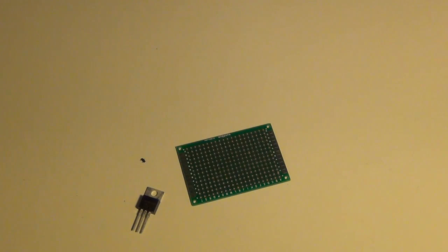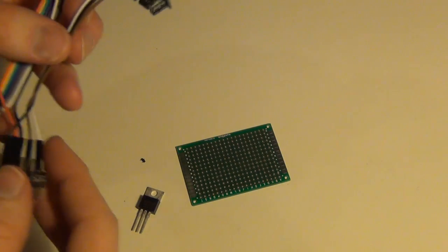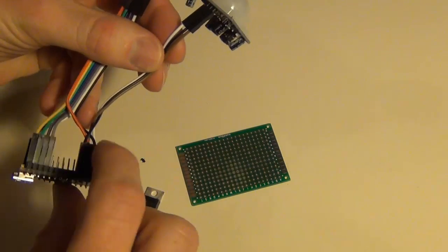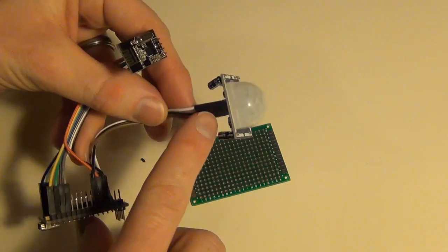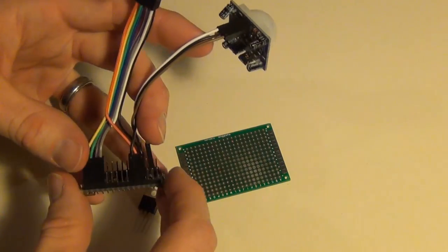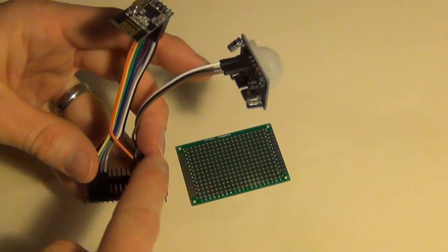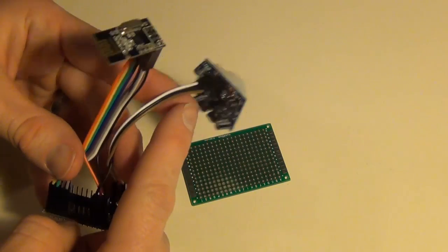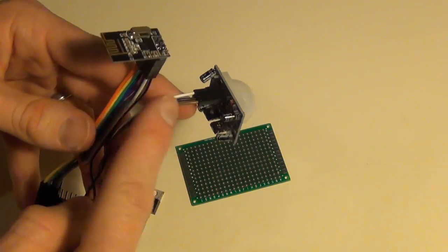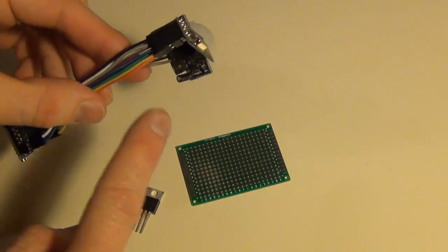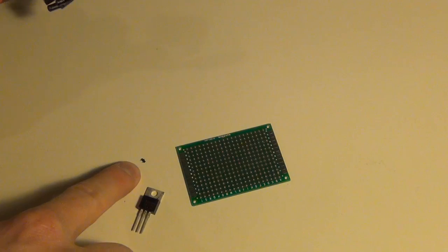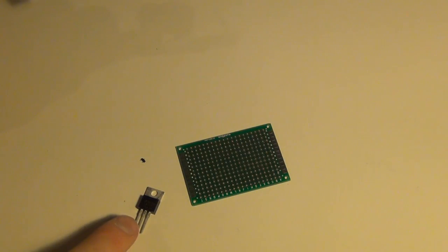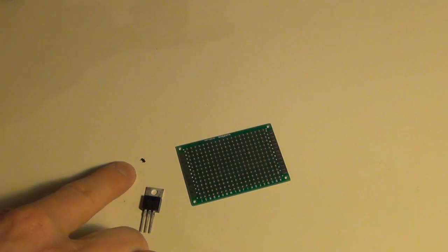So whenever possible, I'll supply it from my external power source. So what that would look like is instead of running the power from my Arduino here to my motion sensor, I would take the power that's going to power my Arduino and then just run an additional ground and 5 volts or 3.3 volts depending on what's required to my sensor. Same goes for the radio. If you can supply it with an external 3.3 volt regulator, this is an example of a larger one here if this is too small to solder in.